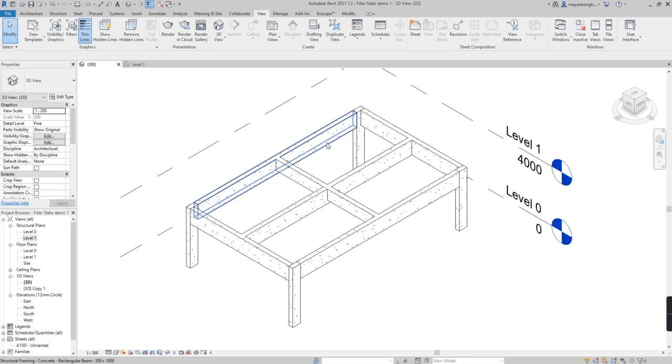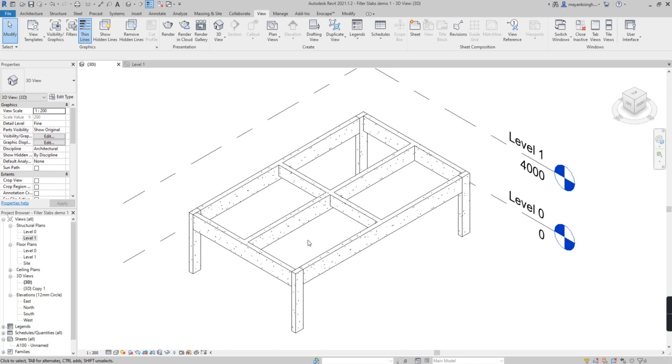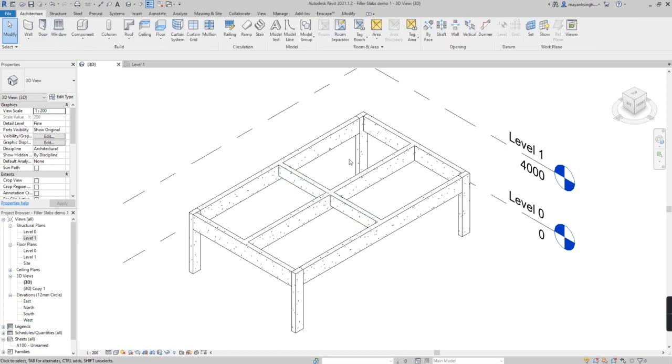What I'm going to do is model 4 materials, and the way to do it is we go to architecture and we'll have to first make the slabs, B, we'll make voids, and C, we'll model the material. It could be a clay pot, it could be burnt brick masonry, normal brick, it could be a Mangalore tile, it could be anything. So any kind of earthy material which acts as a lighter filler material instead of concrete. So I'm going to first go to component and model in place.